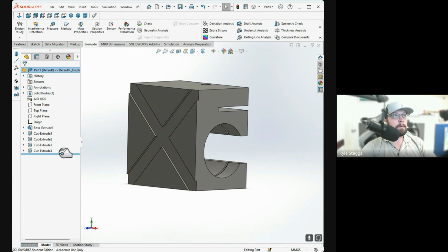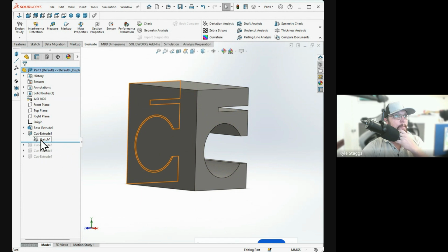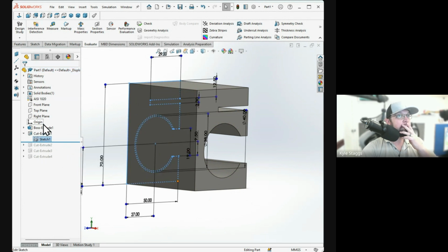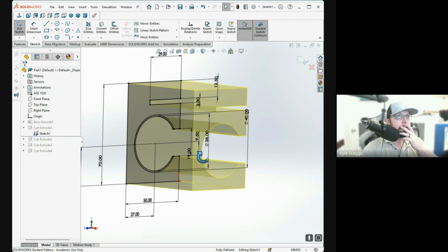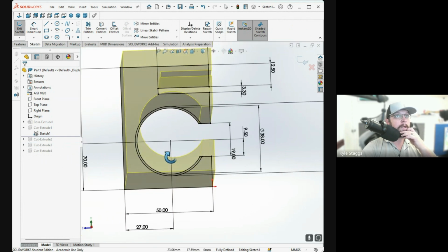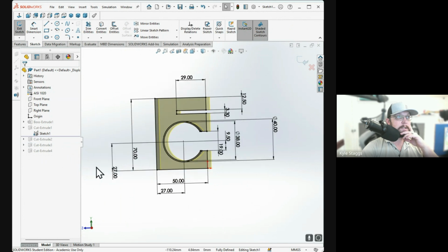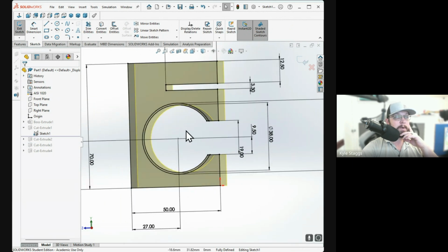So before I did the cuts for the top and the bottom, what I did for these is on the sketch, I have the two circles. I positioned two circles and set the center line distances 27 and 27, so a 27 square pitch.